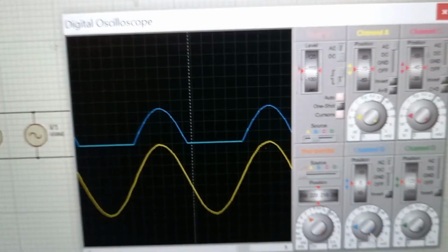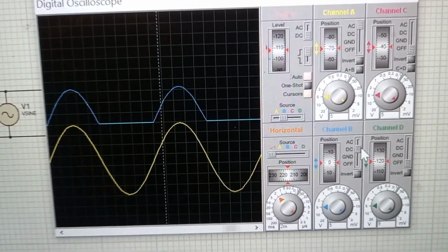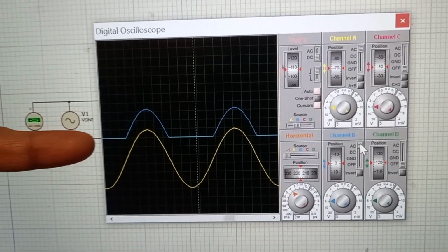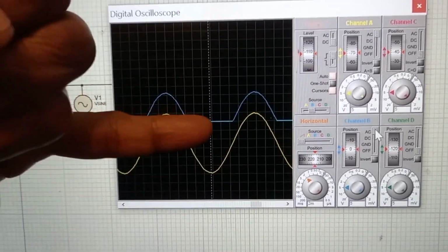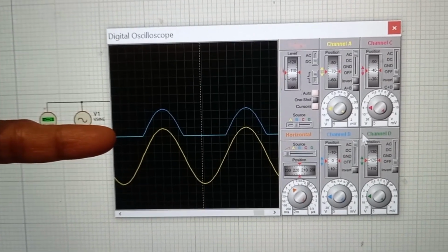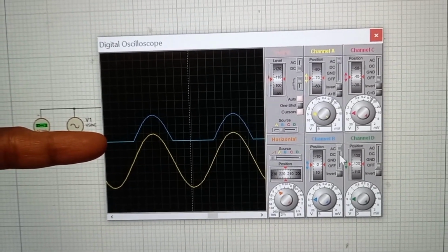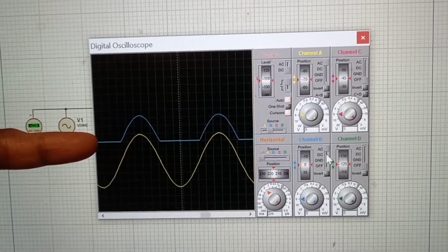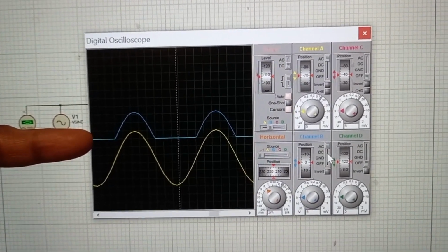How to find the Vdc voltage? First, keep your CRO knob in AC mode and keep your finger on any one of the lines on the base of this output waveform. Now, if you press the knob on DC, the waveform will shift upwards by 1 unit. You just see this.